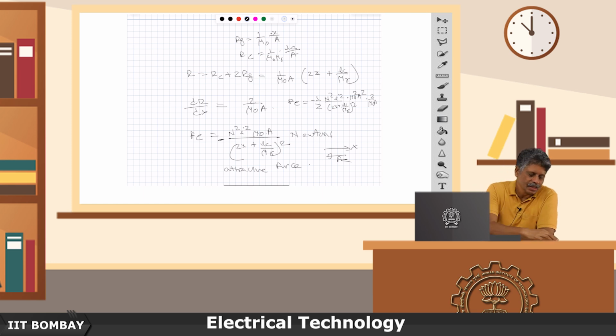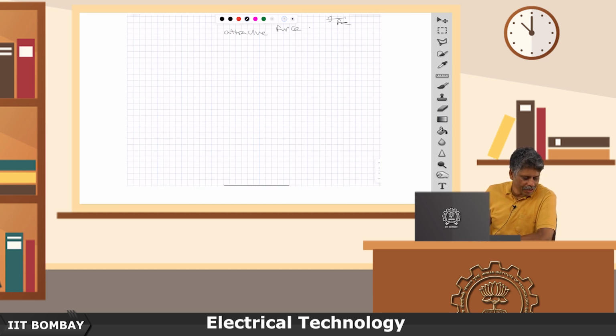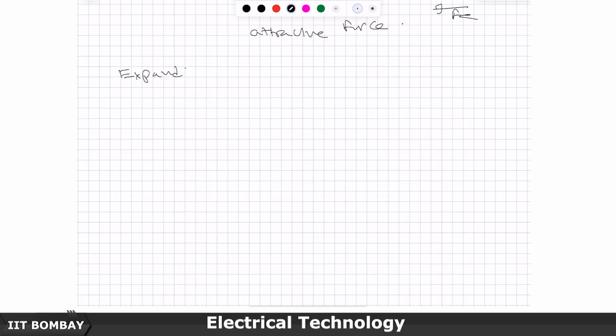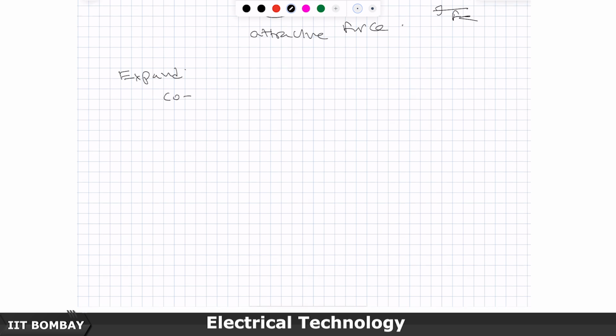So, what we need to do now is take this idea further to a two electrical and one mechanical port system. So, let us expand this. Finally, we are trying to go towards multi-port networks. As a next step, let us expand the idea of co-energy. See, 3-phase windings will have at least a multi-port system; even if rotationally there is only 1 degree of freedom, actually there could be multiple also.